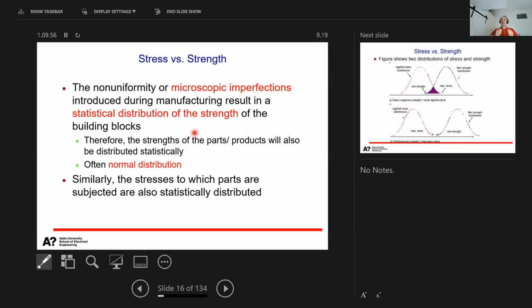And then we could state that this capacitor withstood 963 volts before it burned. But if we take the next capacitor, the value may not be exactly the same, because this strength against voltage is ultimately defined by the imperfections which, let's say, the insulating material between the capacitor plates has. So what kind of defect it has.